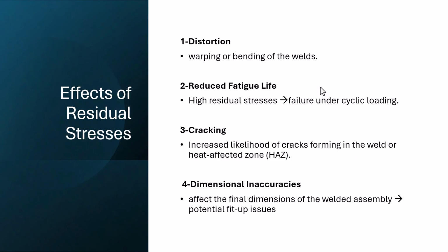So what effects can residual stresses cause? The first one is distortion. As I just said, it can bend the weld, like the shape you saw just before. It can reduce the fatigue life because there are high stresses inside the weld, and under very low cyclic loading it can fail.